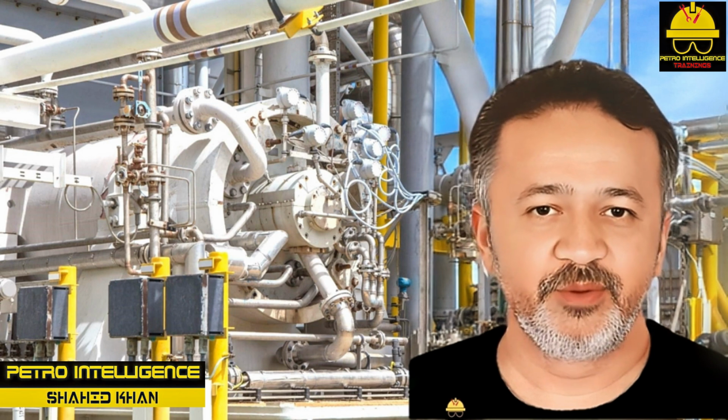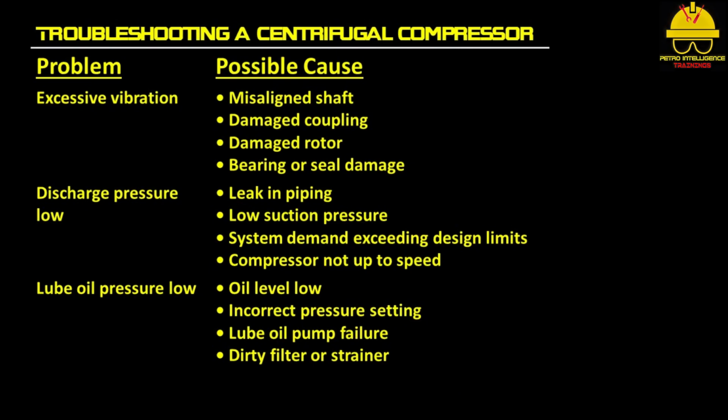Troubleshooting a centrifugal compressor. If there is excessive vibration, there might be misaligned shaft, damaged coupling, damaged rotor, or bearing or seal damage. If discharge pressure is low, there might be leak in piping, low suction pressure, system demand exceeding design limits, or compressor not up to speed.